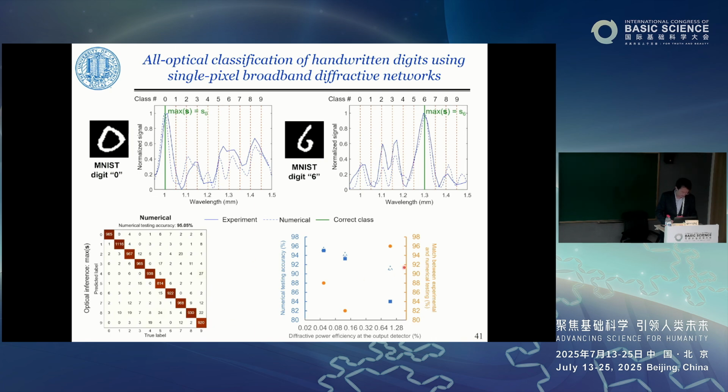Following the experimental demonstration of class-specific diffractive imaging, this research explores a broader concept, from class-specific optical transformations to encryption using diffractive neural networks. As we can see, the network is further implemented at a wavelength used in silicon photonics, which is 1550 nanometers.